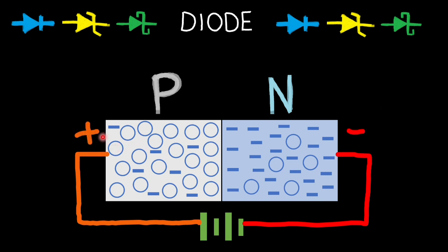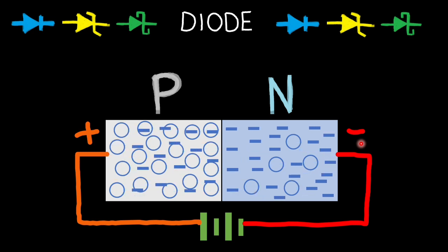When we apply a positive voltage to the p-type material and a negative voltage to the n-type, the positive voltage presents a very strong electric field on the n-type material so that the free electrons from this material will be attracted to the positive voltage terminal. And also, it is further reinforced by the negative voltage pushing the electrons towards the positive voltage. These electrons will jump and hop in the holes so that we will have a current. This is what we call a drift current.